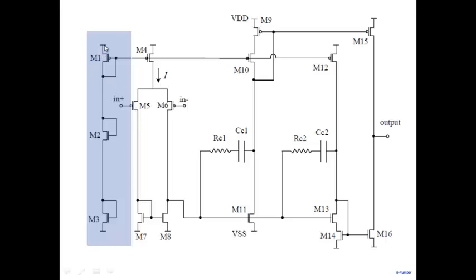Note that what will happen is, suppose you take 3.3 here and minus 3.3 here. Just for the sake of argument, let's say all NMOS and PMOSs are the same. If all are the same, how much will be the drop across each? 3.3 divided by 3, so 1.1, and 1.1 will cause some amount of current to flow. So there's nothing but a current source. It's generating the current for your circuit. Remember I said that what you need is a reference current, and from the reference current you generate all the other currents.